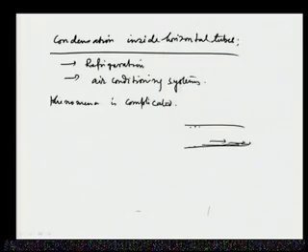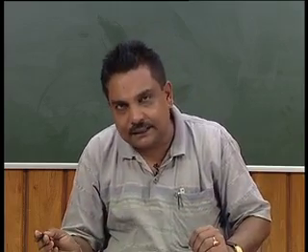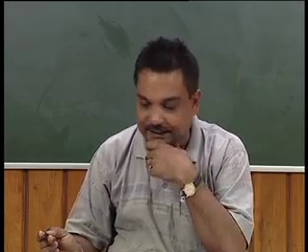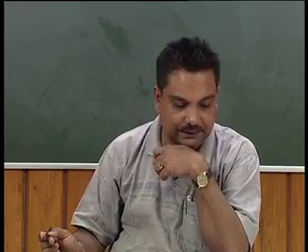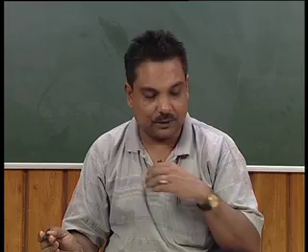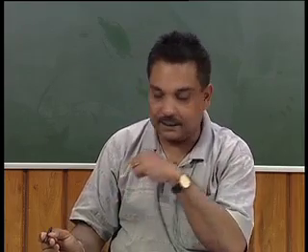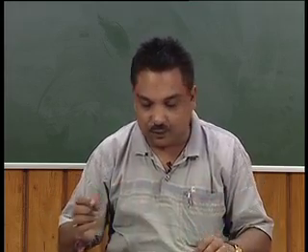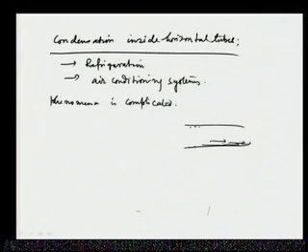When the vapor comes into contact with the cold surface, condensation takes place, but if the tube is short, the rate of condensation is low, and if the thickness of the flowing condensate layer at the bottom is small, then the rate of condensation is low.